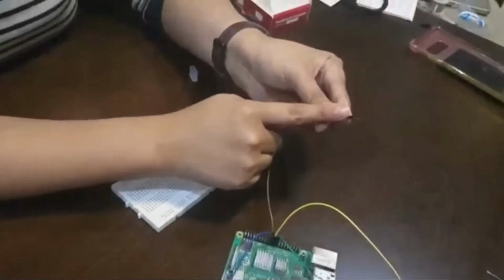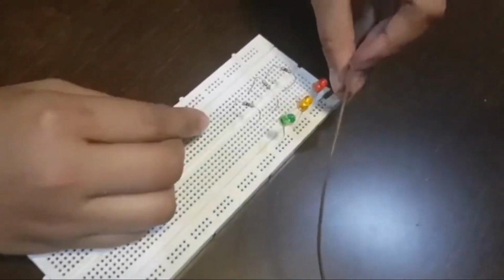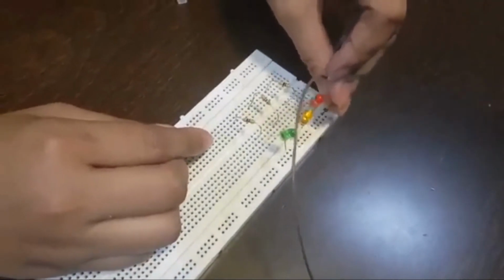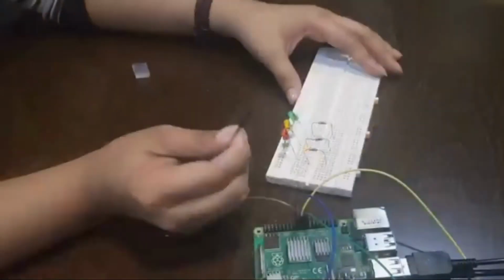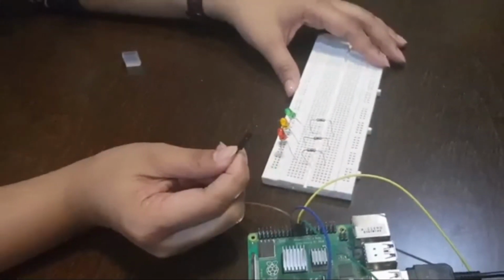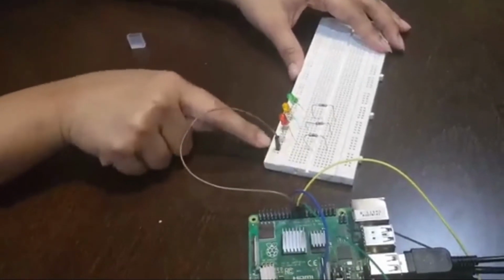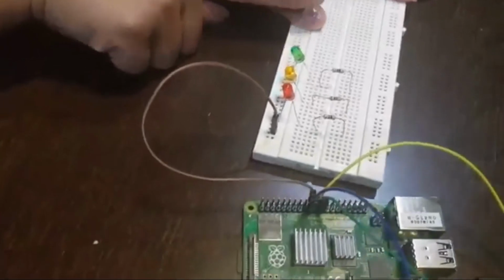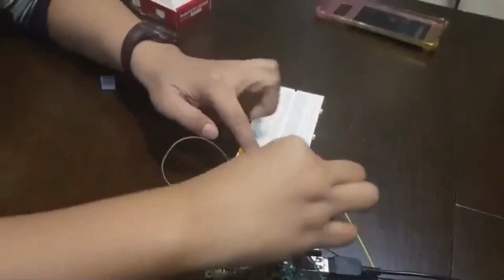After that, connect the ground pin to the node where the negative legs of the LEDs are connected. Remember, only half of the row is connected. The male end of the jumper wires in the GPIO pins can now be connected to the LED resistor series. We use color code to identify the connection easier. The blue jumper is connected to the end of the red LED resistor series, yellow jumper for yellow LED, and the green for green.